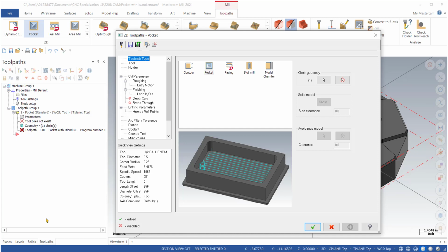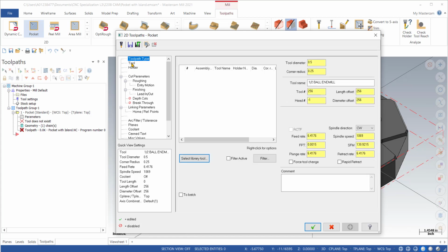As you know, it's a 12-inch part, so it's quite a size. If we try to rough it out with a half-inch tool, it's going to take forever, right? So we're going to rough it out with a 1-inch tool, and then we would do a finish and remachining pass with a smaller than half-inch end mill, like maybe 3/8.